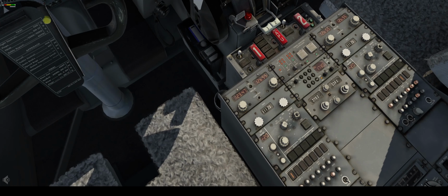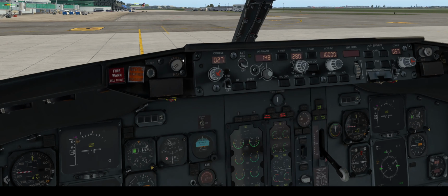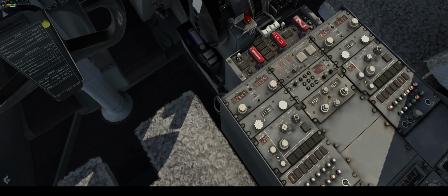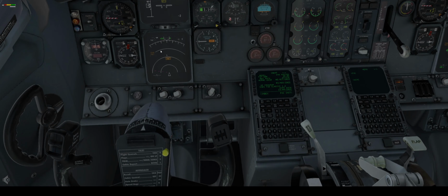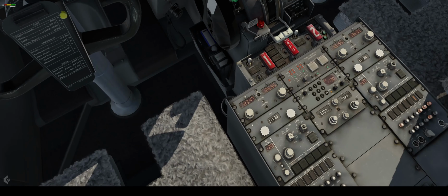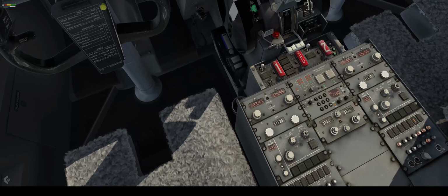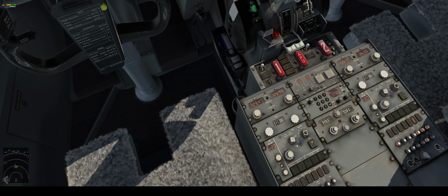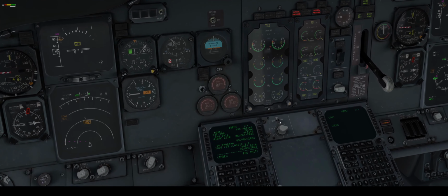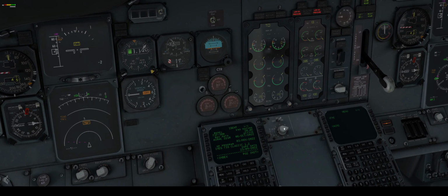And this is the EFIS panel, which is basically on NG right now. Okay, range mode, this is the map mode. Okay, so as you can see right now, basically that's it. What you have to do is, for example, if I would like to press the weather radar, I put it like now, but I need to switch it on here and adjust the tilt antenna here.